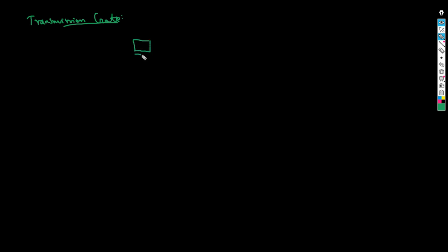Basically, you have your NMOS and you have your PMOS, which is say A, and this is A bar, and this is the input, and this is the output. Now this again is going to give you a strong 1, because your PMOS is going to give you a strong 1, and your NMOS will give you a strong 0.